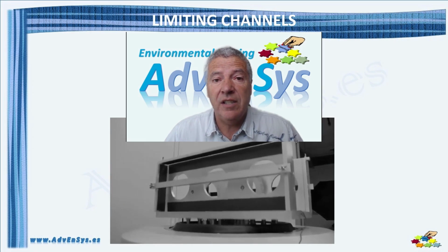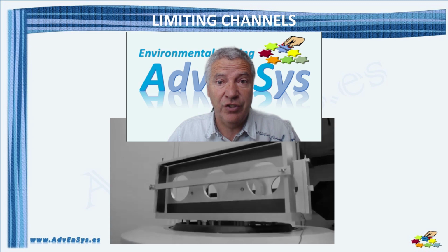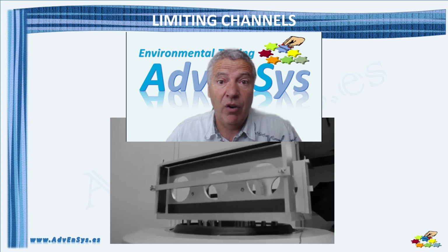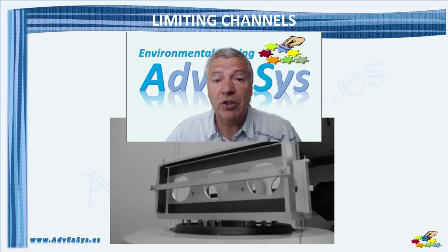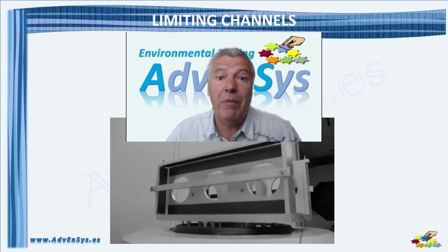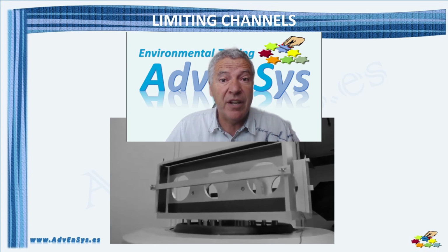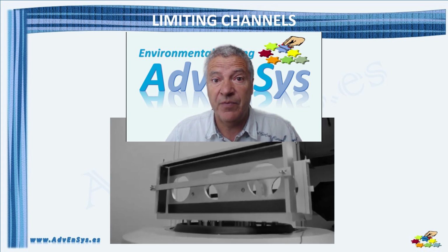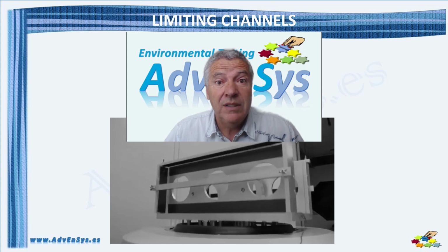Summarizing, limiting channels become a very interesting option for our monitor channels in a vibration test, adding a layer of additional control to protect our DUT and our shaker from unexpected vibration that may appear during the development of the test.